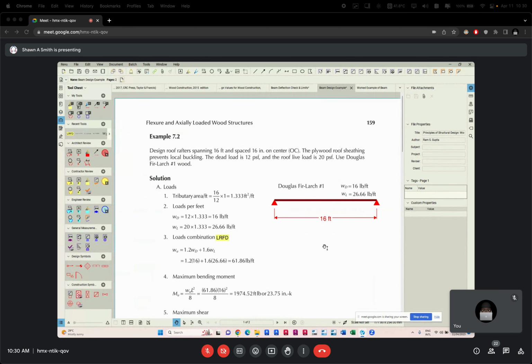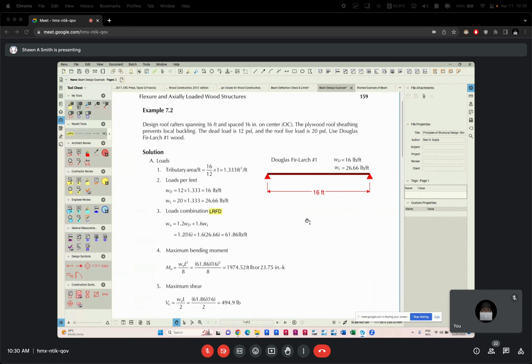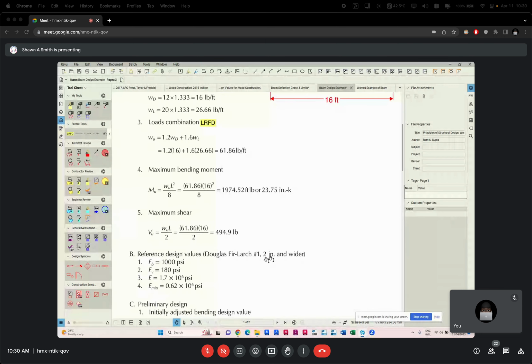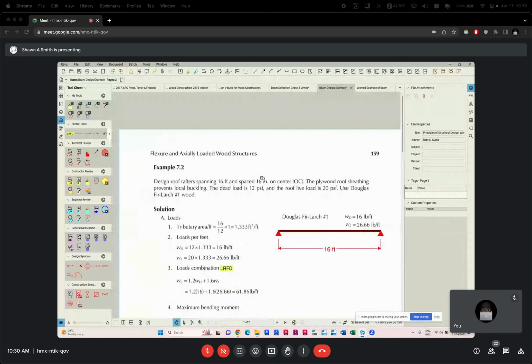So we can assume one size to go in the table with. You can always assume and say, okay, fine, I'm going to use 2 inches thick lumber. It's a roof lumber. So that's what you normally start with, nothing less than 2 inches. And that is why they have gone in the table with 2 inch and wider. It wasn't given up there.